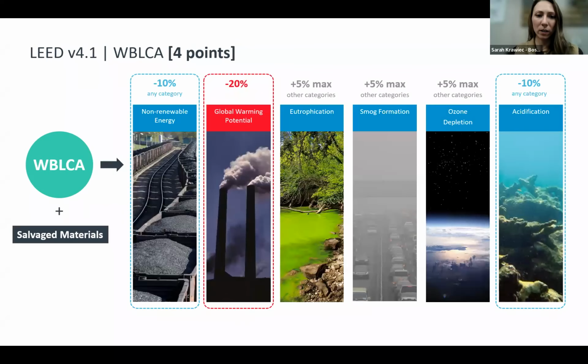So Laura, I have a quick question. In LEED, what is the reduction compared with? Is there some kind of baseline? So would that be the model that you did without any like carbon incentives? Yeah, you get to define your own baseline for LEED. There is not yet enough data that's kind of standardized across the entire industry that you could define like an industry-wide baseline. So it's relying on the designers to establish their own baseline.